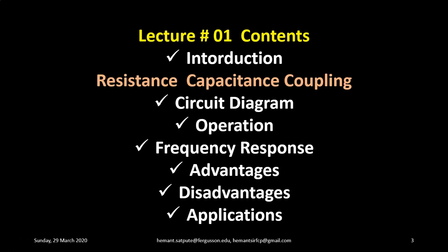In a multi-stage amplifier, the output of one stage makes the input of the next stage. Can we connect the output terminals of one amplifier to the input terminals of the next amplifier directly? This may not always be possible due to practical difficulties. We must use a suitable coupling network between two stages so that a minimum loss of voltage occurs when the signal passes through this network to the next stage.